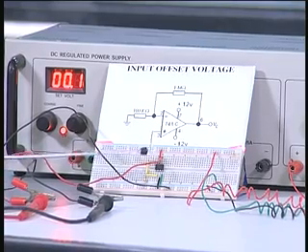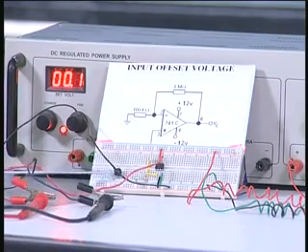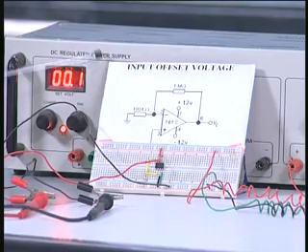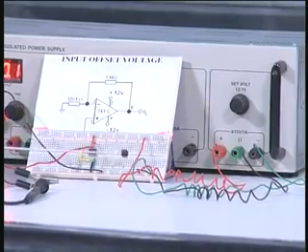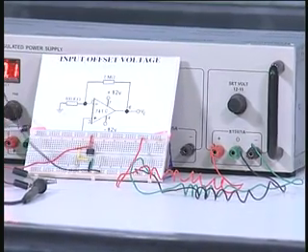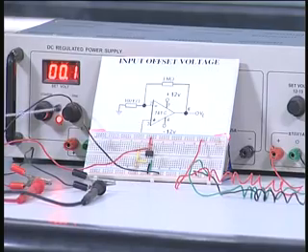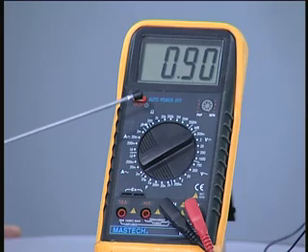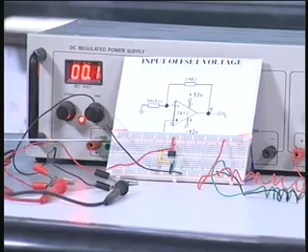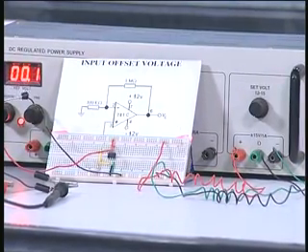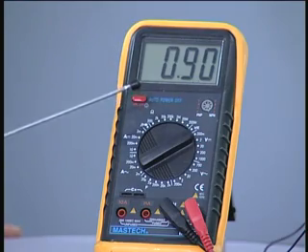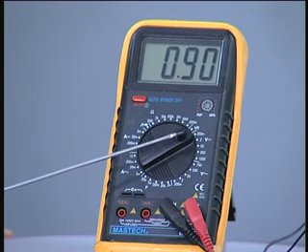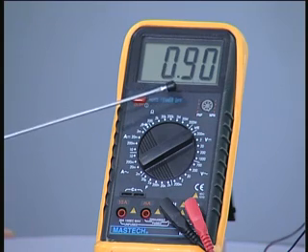You have the op amp, you have the two resistors when you come closer and see, and the wiring is done. This is the dual supply behind, and the wiring corresponds to the plus, minus and the ground connected here, and pin number 6 is connected to the multimeter here, which will measure the output voltage. The two input terminals are grounded as you have seen here, and now let us see what is the reading in the multimeter. You can see the multimeter is in the 200 millivolts range. In that it is measuring 0.9 millivolt.